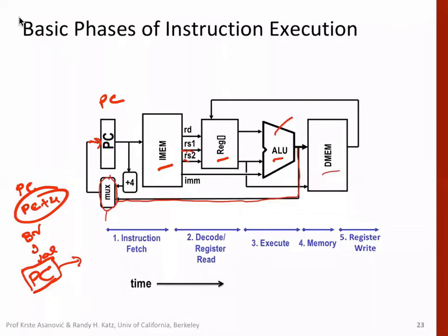You can see the outputs for register 1, register 2, and RD are going out. From instruction memory, we read the instruction, and then the corresponding fields will be read, and there is a register file here, from which we select the registers. We'll come to that a little later, and then we have the ALU. But something that is shown here is that it has 5 phases.